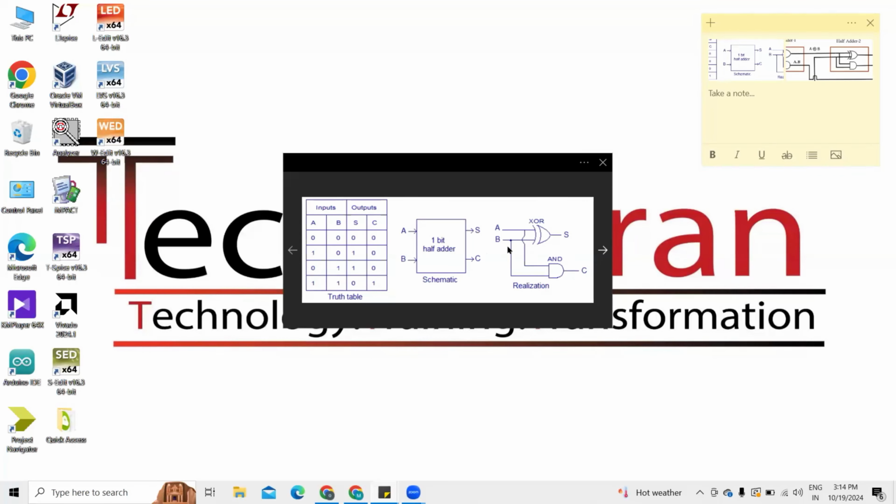If you observe the circuit, it uses one XOR gate for the sum and one AND gate for the carry. Why are we specifically using XOR and AND? If you observe the truth table of this half adder and the combination of outputs under the sum, the combination is 0, 1, 1, 0. This output combination we get from the XOR gate. So to get the value of sum, we need to use one XOR gate.